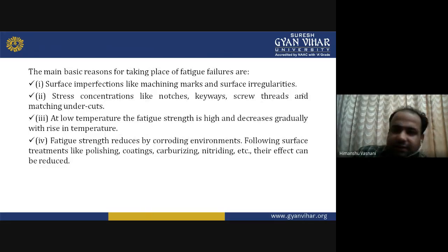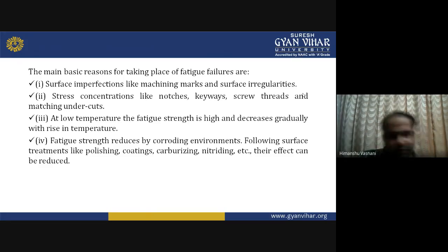The main reasons for fatigue failure are: first, surface imperfections like machining marks and surface irregularities. The second reason is stress concentrations like notches, keyways, screw threads, and machining undercuts.